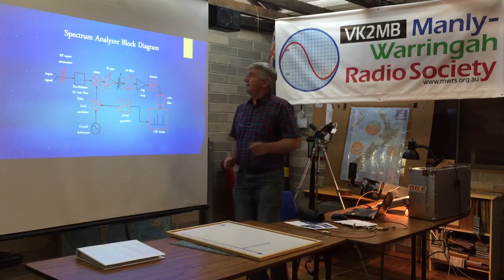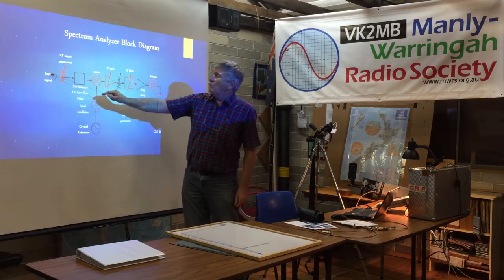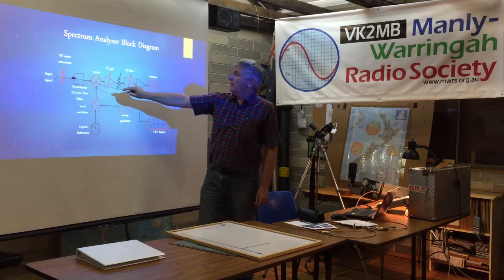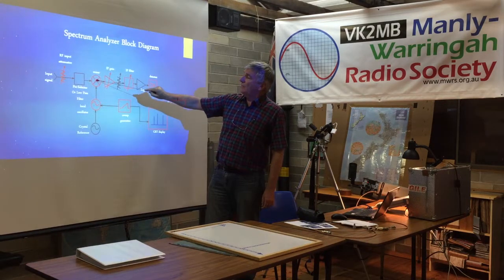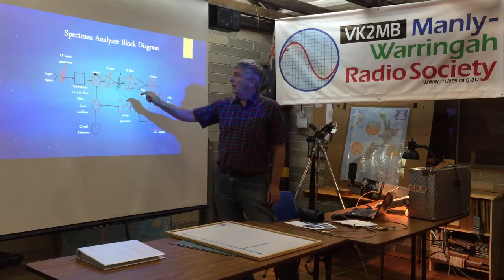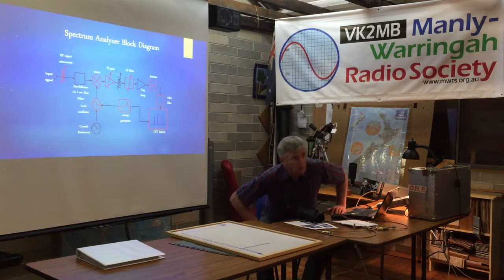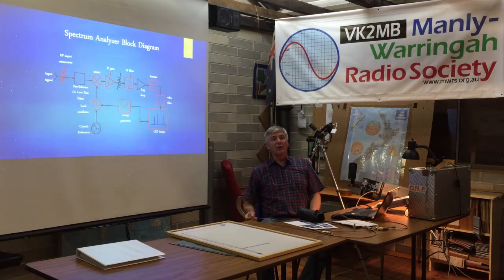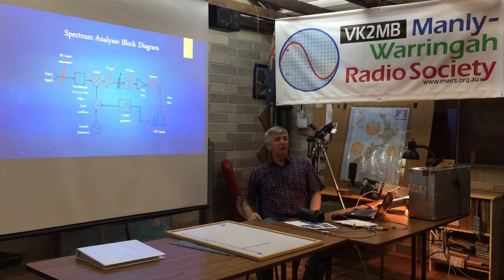I'll say here for the second time, and it won't be the last time, that if too much input signal comes in through here, this front-end mixer gets destroyed. And as I said, these things typically go to gigs or tens of gigs, so just imagine how expensive this little baby is. They are incredibly expensive. It happens over and over again that people accidentally transmit into it. This mixer gets destroyed, people go ask for a quote, and in the end they usually throw the thing out and buy a new one.